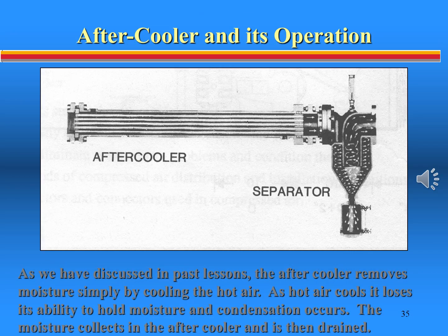This process of moisture removal begins at the aftercooler. This device, as its name implies, is located after the compressor but before the receiver tank. Its principle of operation is that of condensation. The air coming from the compressor is hot and heavily humidified. As air enters the aftercooler, it is subjected to cooler temperatures, causing the moisture to fall out of the air and to collect in a section called the separator. Since air is lighter than water, the air moves up and out of the separator while the water remains and is ejected from a valve or other device that allows it to escape from the system.